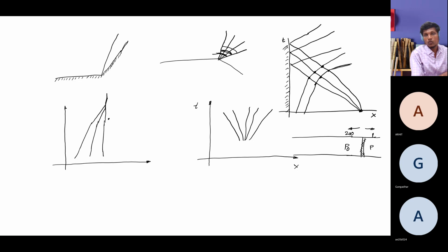These characteristic lines are not straight lines. If you try to draw characteristic lines in this expansion fan, this is one characteristic line. And if you draw at this point, this is right running or this is left running, these characteristic lines are also present, but do not represent an oblique shock wave. Try to draw the things in the flow phenomena, then you will get a clear understanding. Though it is leftward running, backward running expansion wave, those expansion waves do not form an oblique shock.